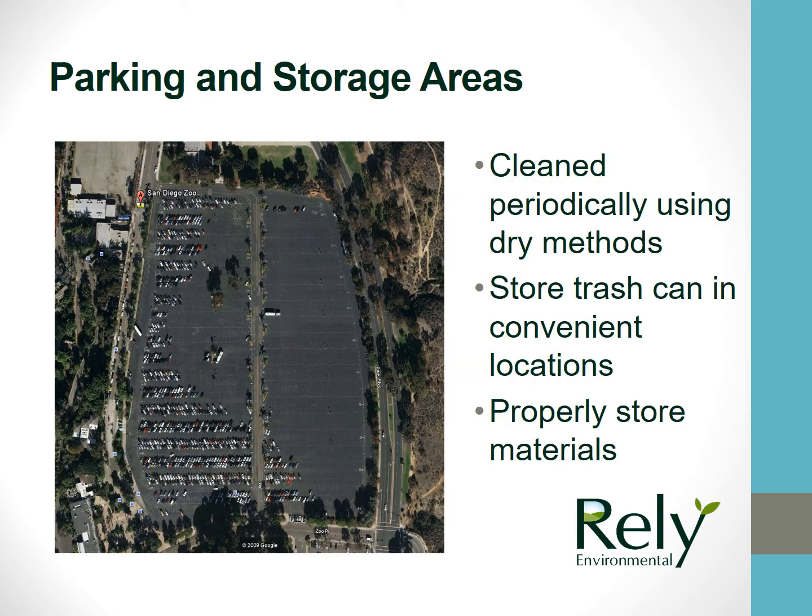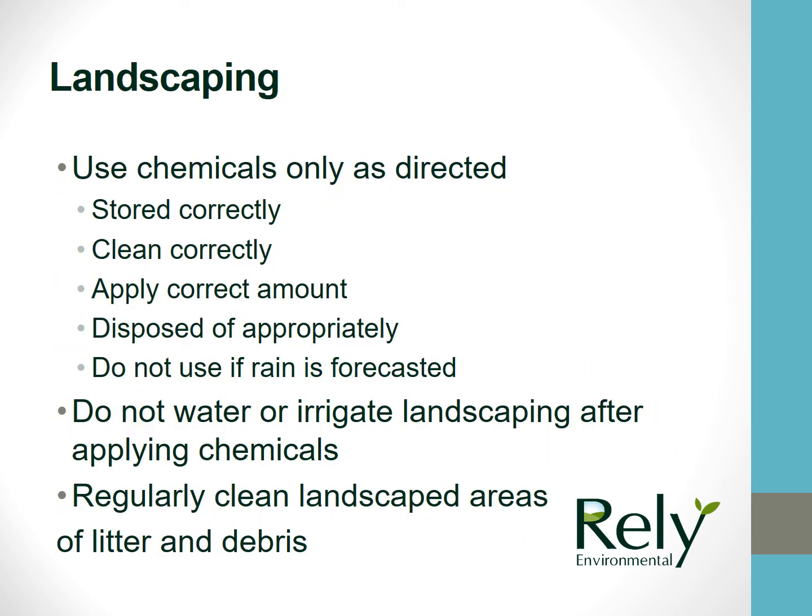Parking areas tend to have more contamination, seeing that they tend to have a lot of traffic. They should be cleaned periodically using dry methods. Have trash cans in convenient locations to prevent littering from the public, and have materials properly stored to prevent contamination of runoff. For landscaping, use chemicals only as directed on the packaging.